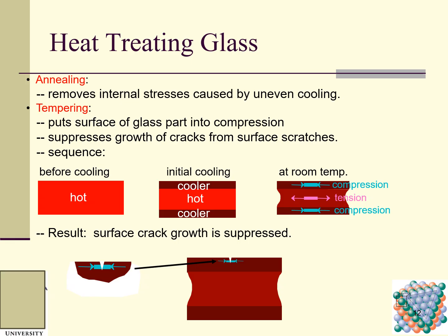I also told you guys when we talked about case hardening. Case hardening means that we put some samples, specimens, in a sealed chamber with a small amount of carbon source, for example a liquid or a gas such as methane, CH4.